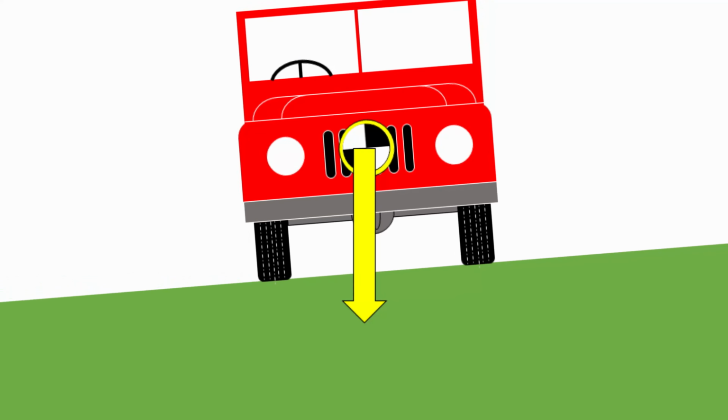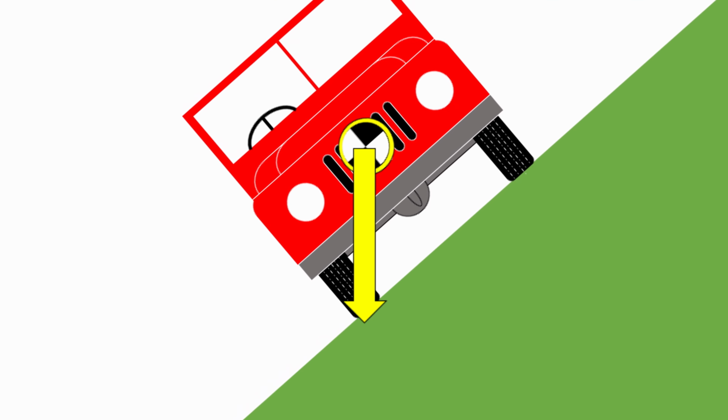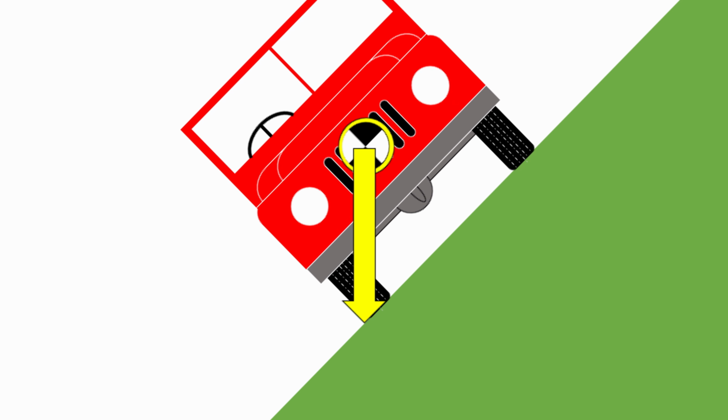When we're testing vehicles, testing their stability, we normally do that on a thing called a tilt table. So the idea of a tilt table is that it's a platform that you drive the vehicle onto, and you can tilt the platform up progressively until the vehicle becomes unstable. And normally we do that up to the point where the uphill wheels start to lift away from the platform.